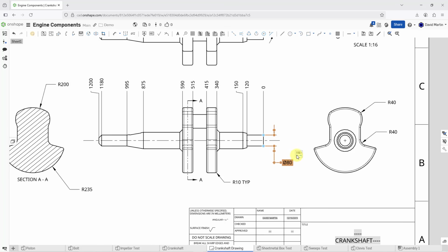If you put your mouse over the dimension palette, it will expand. In the bottom right-hand corner is a control for dual dimensioning. By default, it is set to single units for the drawing. You could change it to single units where you display a different unit, or we can choose the bottom option for dual units. I will click on that and then deselect everything. And you can see that the dimension now appears in dual dimensions with the secondary dimension above the primary dimension.